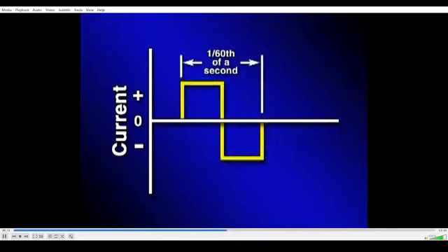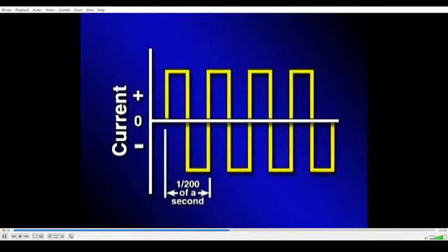With inverters, you can vary the frequency from less than 60 Hz up to several hundred cycles per second. A frequency below 60 Hz provides a soft, wide arc with a wide weld bead, a wide cleaning zone, and shallow penetration. As the frequency increases above 60 Hz, the arc cone becomes narrower and the arc pressure increases. This provides a more focused arc with deeper, narrower penetration and less arc wandering.